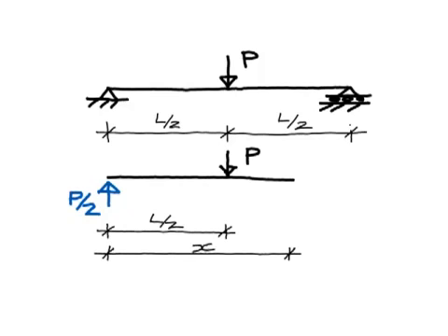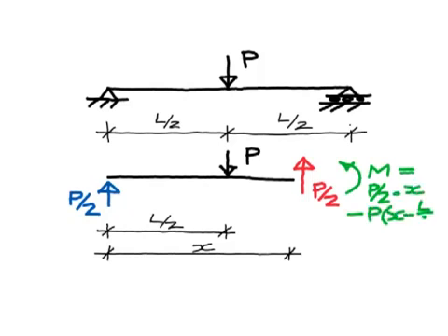And again, this free body would rotate were it not for the bending moment M, which exists at the cut. And in this case, the bending moment is slightly more complicated than before. It's still fairly easy. We just have two loads to worry about, two distances, and we can calculate what the bending moment is at the cut.